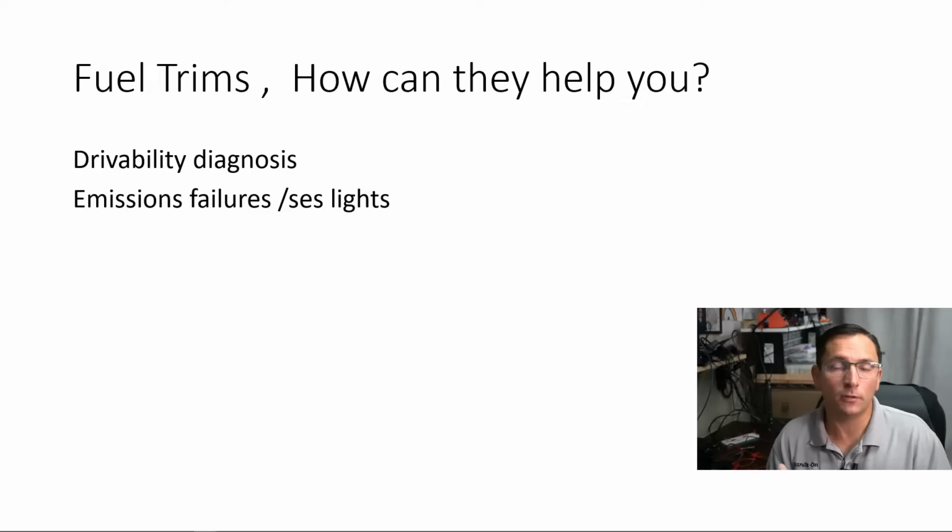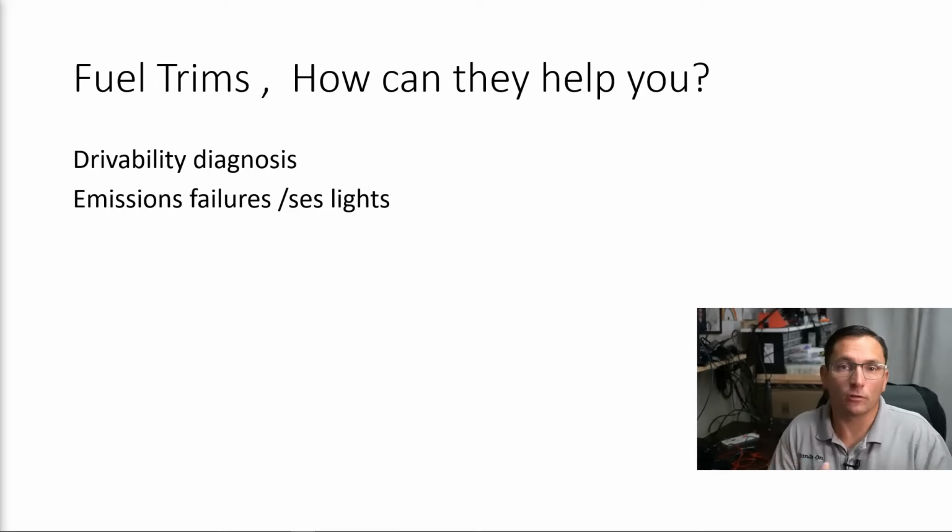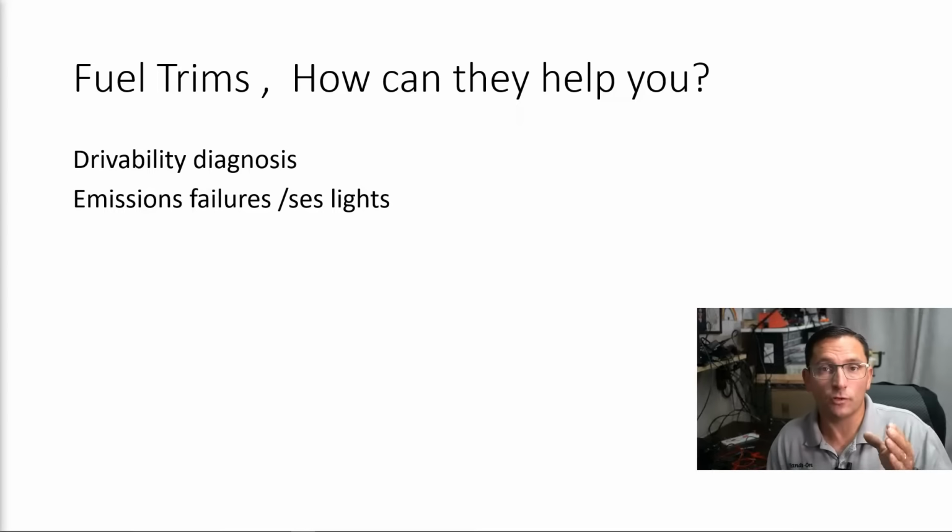If you're dealing with a misfire condition and you're trying to figure out, well, is it an injector or is it a coil? Fuel trims can help you determine that. Understanding what the fuel trims are and how they work can make a big difference in your diagnosis. As many other instructors have said, and I agree 100%, we've got to go for the low-hanging fruit. What's easy for me to look at without getting dirty, without having to take apart the car, and fuel trims are one of those things that give us easy access to determine what's going on with an engine. This is just another tool in your belt to help you diagnose a vehicle.